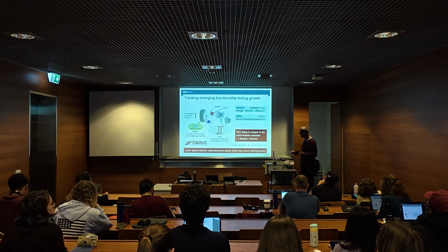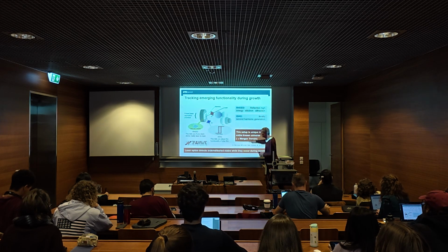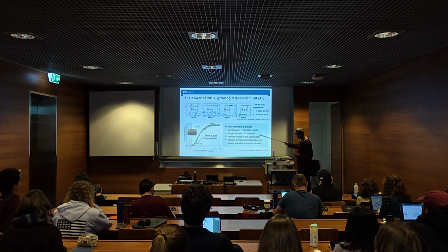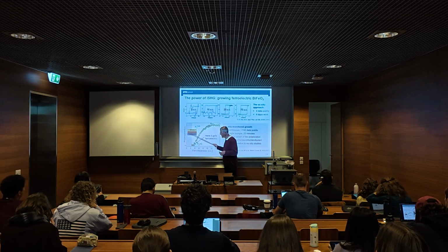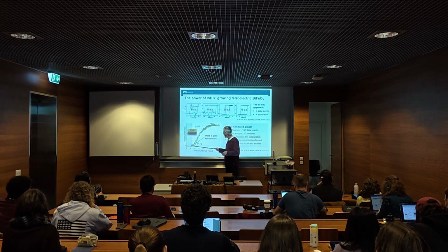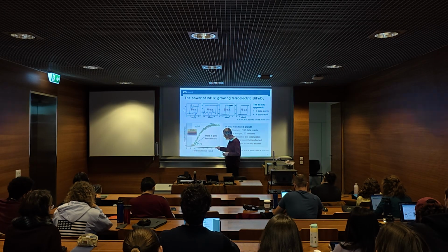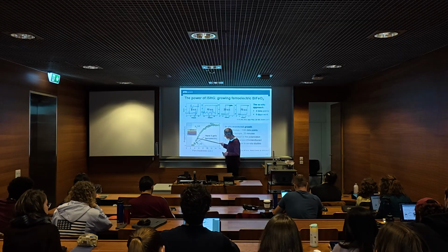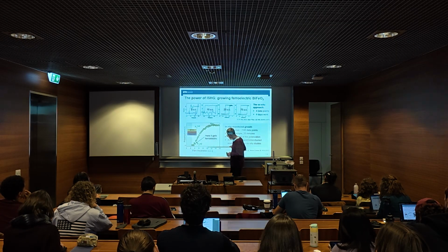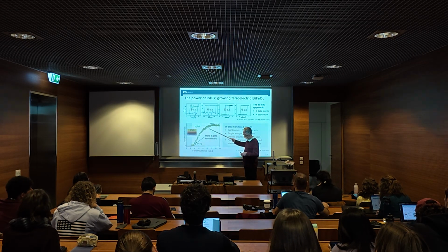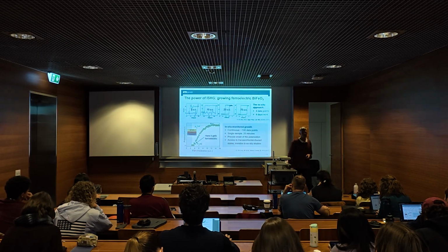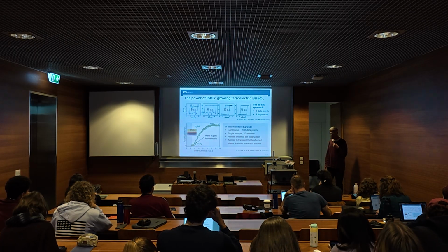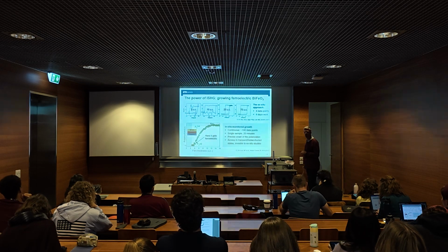Now we take this setup, we measure while we grow. Now you get 100 data points in 20 minutes. So here you see, while you grow a bismuth ferrite film, this frequency double signal, and it stays 0 until you have 3 monolayers, 3 atomic layers. Then the signal comes about, increases, and after the 10th monolayer, so 10 atomic layers, it behaves like a barcode signal. That's immensely powerful, because now you can really track what is going on during your growth, and you can counteract it.